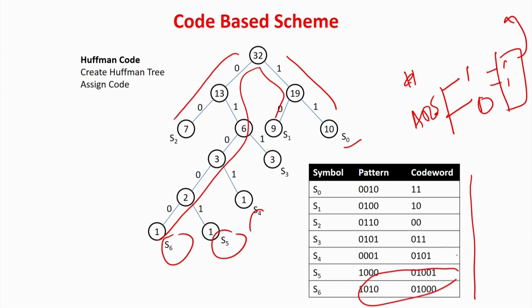People might think that there are many patterns which occur at very low frequency, but if you use them for encoding, your decompressor circuit may be large. So one option is to take only the most frequent code words and code them using, in this case, Huffman code, and pass the others directly, so that the decompressor circuit does not take more area. Only for the rarely occurring patterns do you require more width of the ATE. So once in a blue moon, when one such pattern is applied, I will take all the channels of the ATE rather than making the decompressor circuit too large.